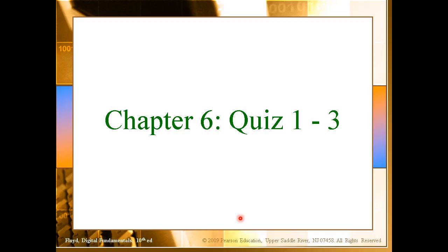Now you might be wondering, we are talking about the adder, so how can we do subtraction? Let's recall how we do subtraction. Remember at the very beginning of the class when we learned binary subtraction, we had a couple of steps. We flip the number first to make it a 1's complement, then we add 1 to make it 2's complement, and at the very last step we add both numbers.